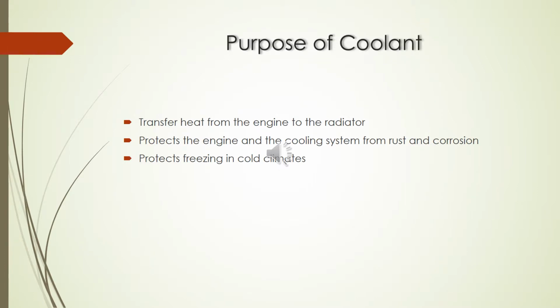What is the purpose of the coolant? The coolant is a heat exchange medium. It's there to transfer heat from the engine to the radiator. And moreover, it protects the engine and the cooling system from rust and corrosion. It also protects against freezing in cold climate. This is one of the primary importances of the coolant, to stop freezing, because we know that during freezing the water